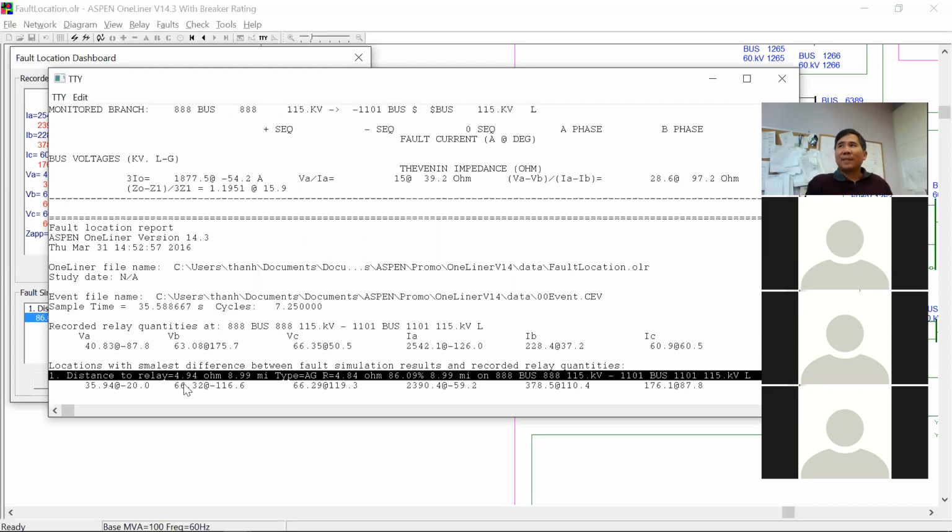And we found from experiments and trials with real numbers on a real system that this fault location is performing quite well. It's quite insensitive, quite tolerant to a lot of different network conditions. For example, whether you have a low load or high load, or you have mutual coupling, it seems to take all those into account, searching with the same accuracy or better than the normal relay report. So I guess that's it.